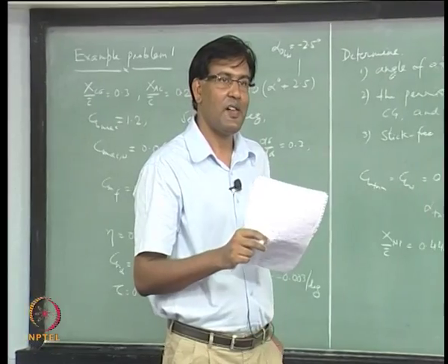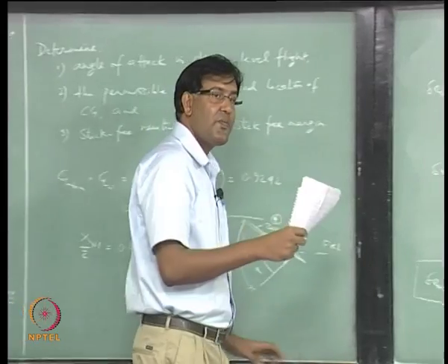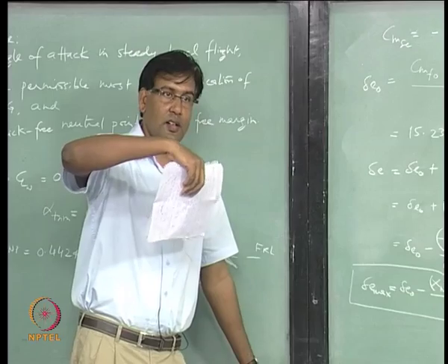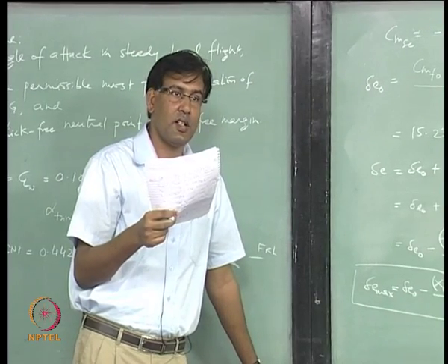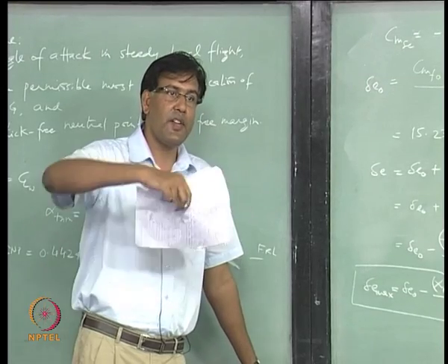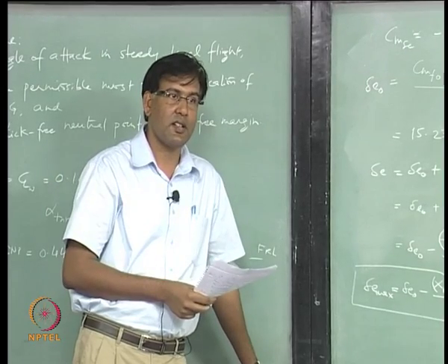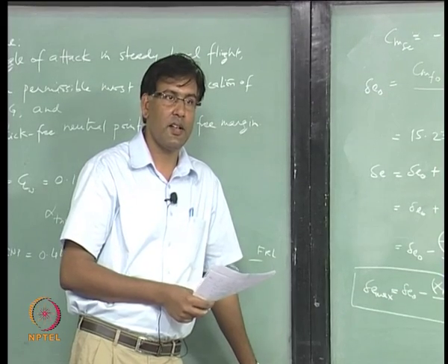And also if CL is maximum, then if you substitute CL max, then delta E will be minimum if you put a minus sign there. If you see that boxed expression, delta E is maximum up. Up is what? Up is negative. Up deflection of elevator is negative.